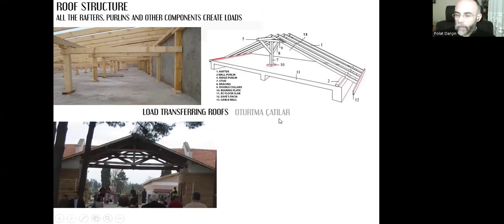What if there is no floor, only a span, a gap? Here we see that there is this structural system, the building, and another structural system building, but there is nothing else in between. There is only one single gap. And if you want to create a roof, that means there is no available surface for us to transfer the loads. Here we need to design a suspended roof.